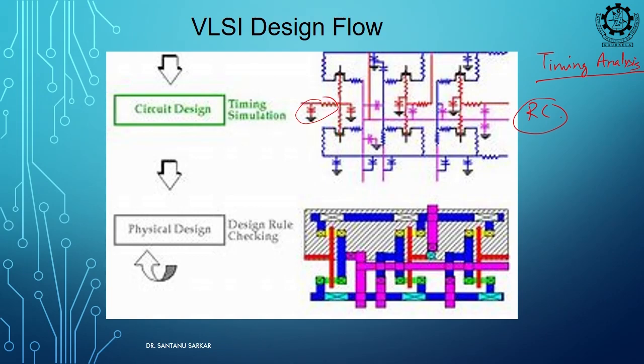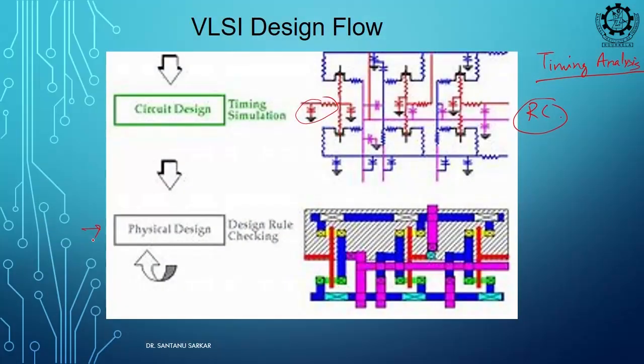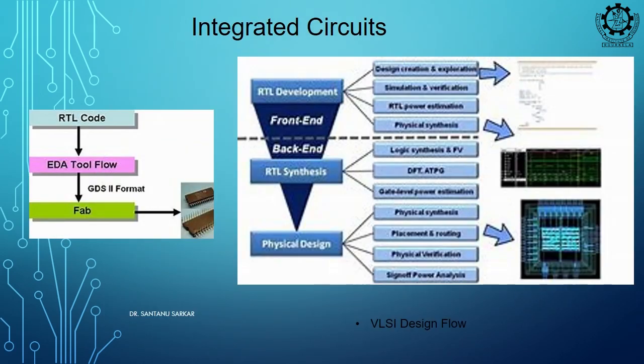So, nowadays even for schematic simulation there is an option for considering all these RC delays. In layout also, in physical design, after layout we do a post layout simulation. In this post layout simulation we do RC extraction. Suppose you have a connection for A and B, these are just wires, right? Ideally they should have 0 resistance, but when you are placing they will consider the resistance and parasitic capacitance for all of this and will give you the final delay.